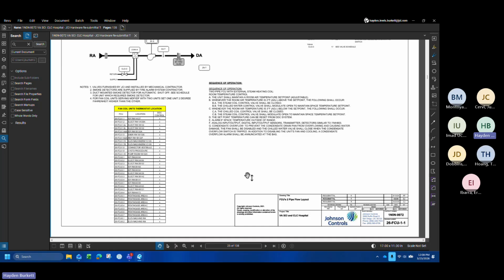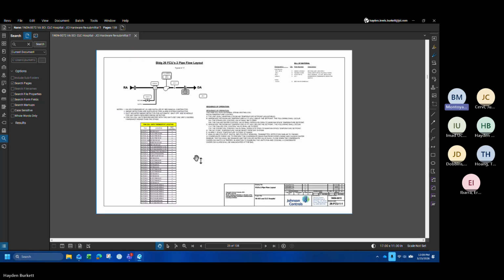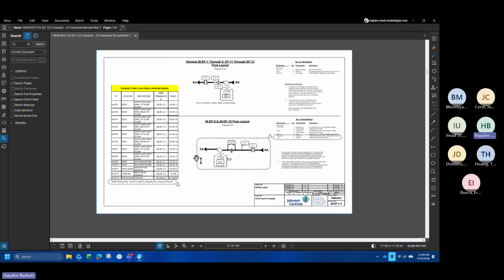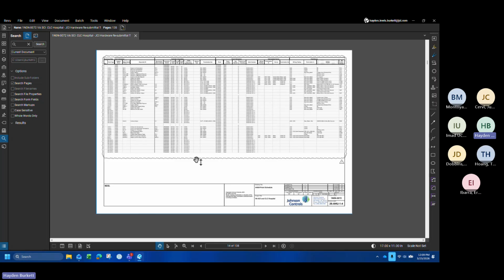We've seen it work okay at like 44 degree water, but I think the sweet spot is really that 43 that was identified. Is it written down in this submittal, sort of like the range of maximum efficiency in operation? I don't know about the control submittal. It's likely written in the mechanicals.